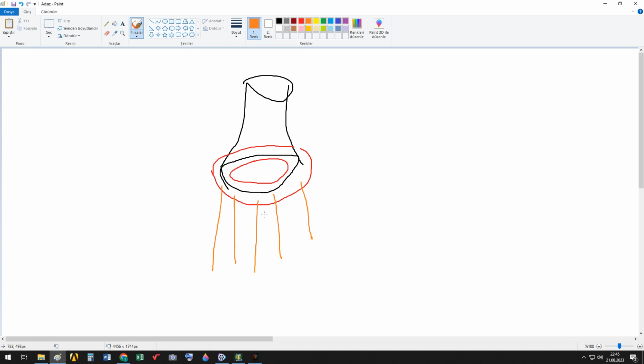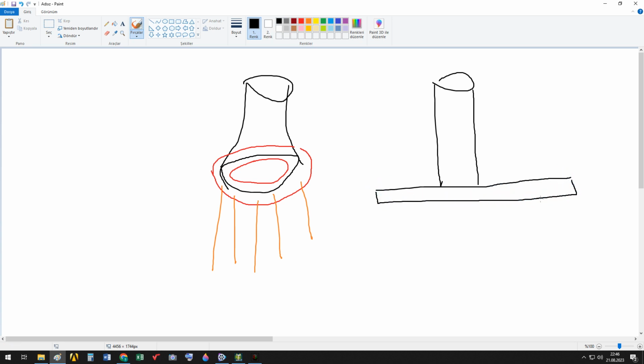What I want to say is, it's better that the caps or the piles are connected with each other. This is the same as for chimney constructions. Consider a chimney. Generally, those structures are thin, slender, and very tall, but because of the bending moment acting at their bottom, their foundations are also very large. And generally a mat foundation.